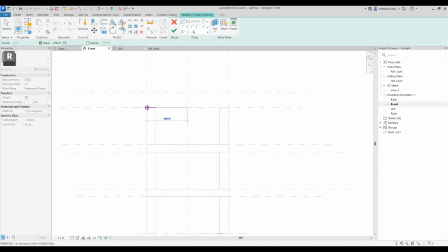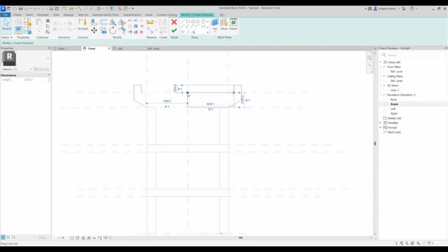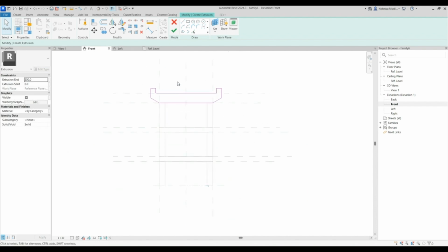We can start from this point, go to the left by 5.5, diagonally at 2000 millimeters at 150 degrees. And then you can take this to the top by, let's say 2000, take it to the right by 1000, take it down by 1000, and then bring it back like this. Select this, mirror it towards the other side, remove these two lines, and just join it as a single line like this so that it makes it easier when you want to apply your parameters and move it.